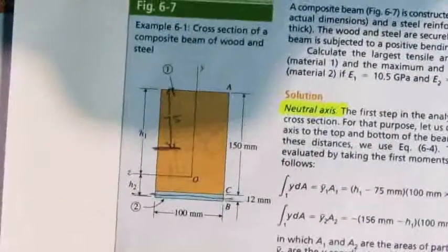So if I were to use the right hand rule, so I shall do this. That is our Z. If I can just zoom out a little bit. If I were to use the right hand rule, I'd basically say this is my hand, and you notice that my thumb is pointing along the Z axis there, and that is the kind of bending that this cross section will be seeing. So you'll see that my fingers are going into the page, and therefore these forces are going into the cross-sectional area at the very top there, and therefore that side will see compression.